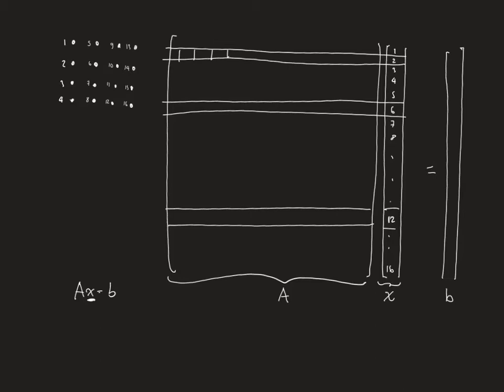And let's assume, because I'm designing the problem, that these nodes in here will have this Dirichlet boundary condition, which means that I'm already imposing a given value of the temperature. So I want all this wall to be given, let's say, 100 Celsius. So we will know that T1 is equal to 100, T2, T3, T4, all of them are going to be given this number 100.